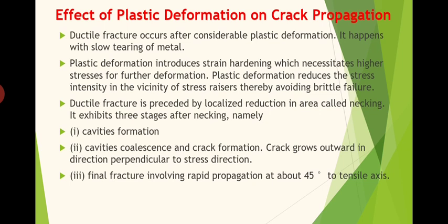Plastic deformation introduces strain hardening, which necessitates higher stress for further deformation. See, once the plastic deformation has started, strain hardening is introduced within the material. So to deform further plastically, we are required to provide much more stress than the initial one. Plastic deformation reduces the stress intensity in the vicinity of the cracks, thereby avoiding brittle fracture.